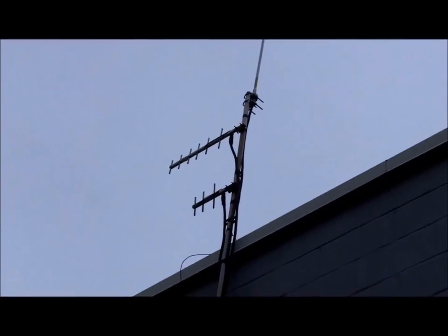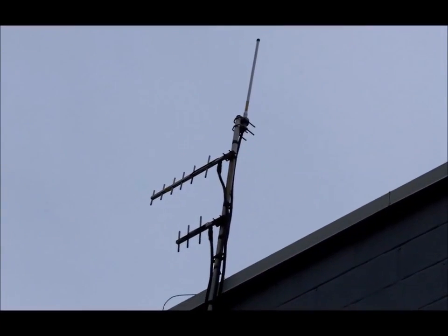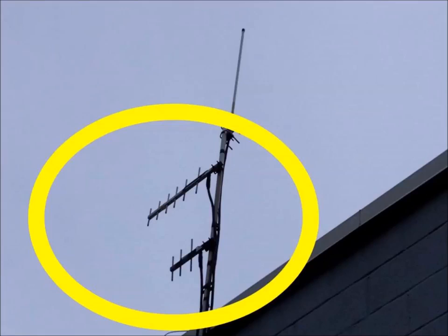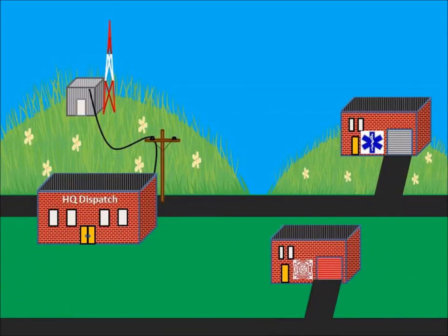Because you're talking through the repeater and not directly from your radio to the users in the field, the antenna can be of a higher gain and directional, aimed at the repeater site location. They usually don't need as much transmit power as a mobile subscriber because of their fixed location and gain antenna, and generally don't need as much power as if they were talking directly.